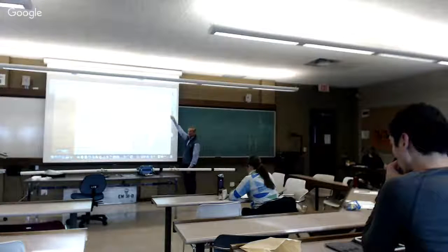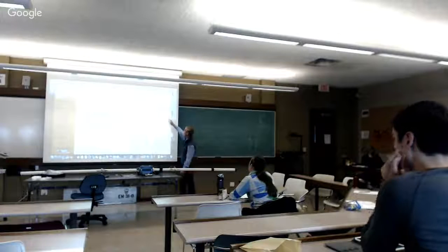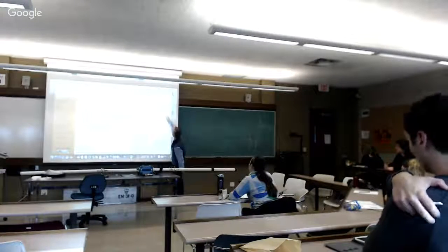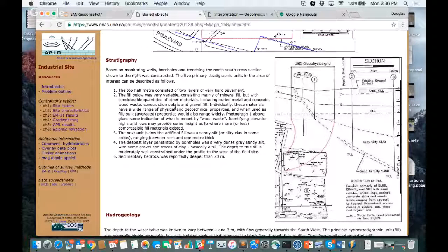When you look at what's happening in a cross section at the Expo site, however, things are much more complicated, and that's probably very similar to what's going on at Chris's place. This is a vertical cross section. From the bottom, we've got the till layer. So at this point, we're fine. And then we gradually go up. The surface has got fill. This material up here is everything from cement slabs to wood products to virtually everything you can think about. And then you've got a clay silt under here, so that's natural. And then we've got the till.